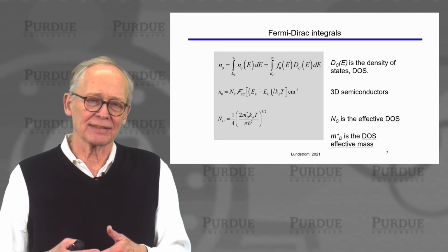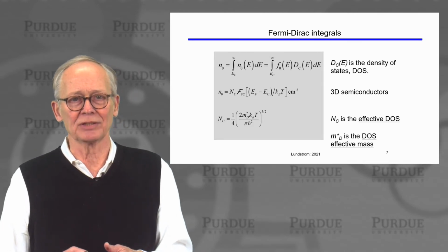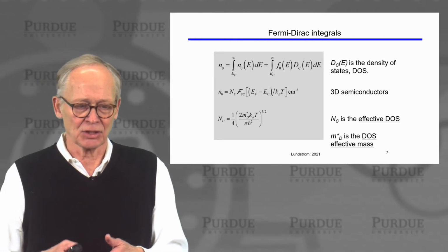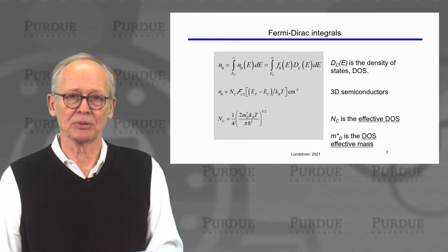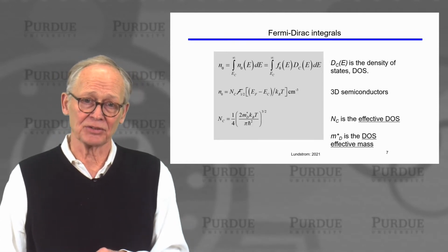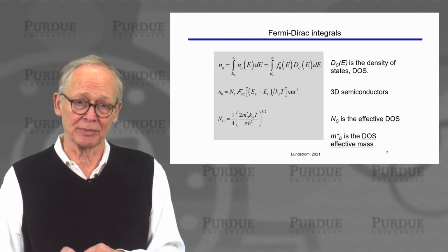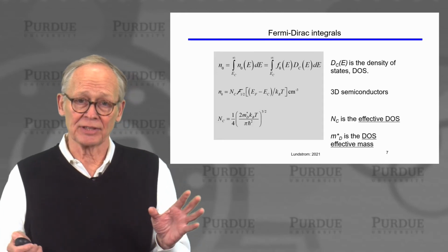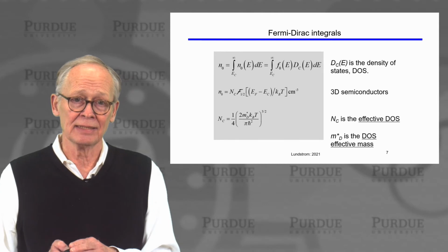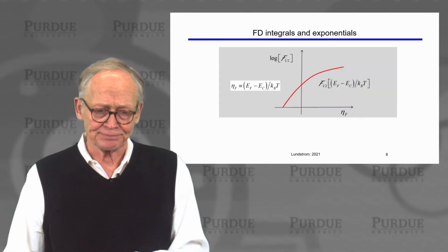If you wrap all of that together, we can put it together in some quantity that we call the density of states effective mass. So it allows us to use this simple expression if we use the appropriate combinations of masses for the particular semiconductor. Oftentimes for simple semiconductors, it's just a simple band curvature near k equals 0.